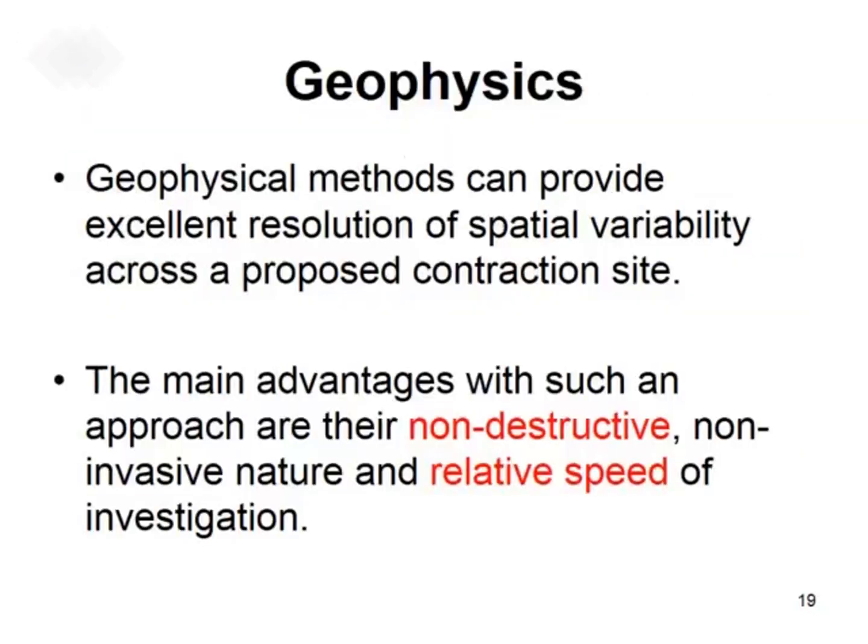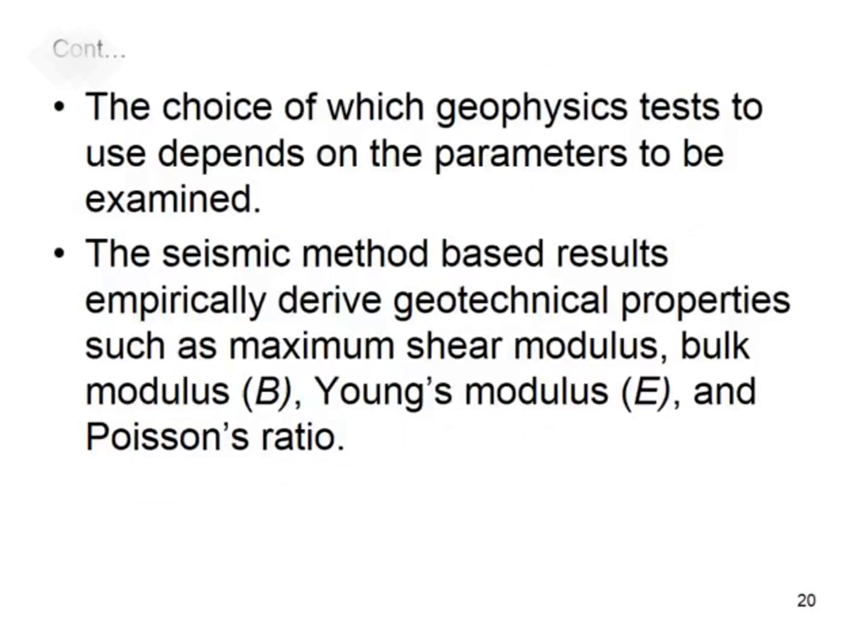So we have finished the geology investigation. Now we go to the geophysics investigation. For geophysics, this method is actually non-destructive, because they use some device to check the underground. Then the selection of geophysics method depends on the parameters to be checked, for example, the shear modulus, Young's modulus, and so on.